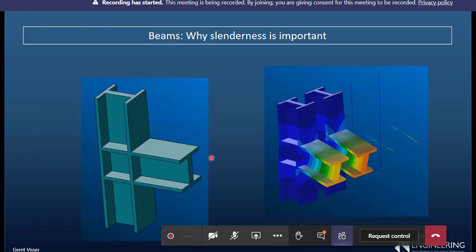Good. If I change it, let's add some stiffness. Again, it's not the best way, and this is typically not how it's done. I just want to show the effect of this. I add some stiffness there to try and stiffen up the section at the back, so that the beam section for this model behaves a bit more like a beam. So the shape at the front and the back is now closer to the same. Already I can see a difference in the answer between these two.